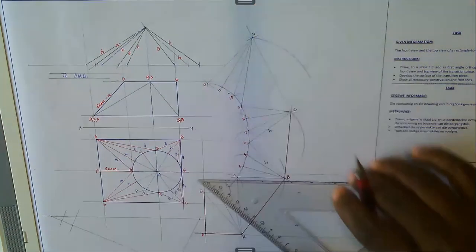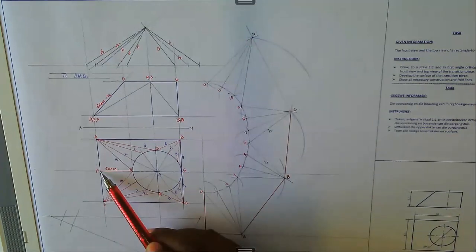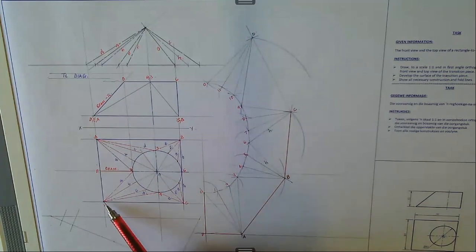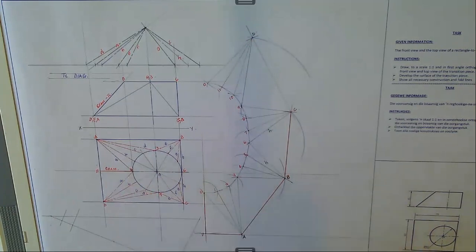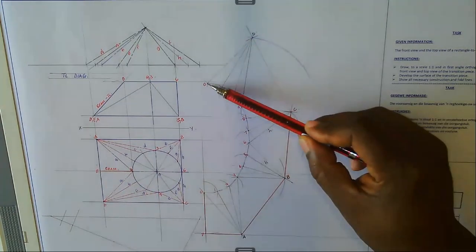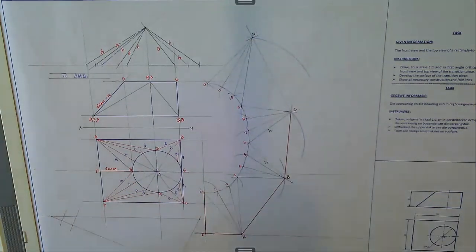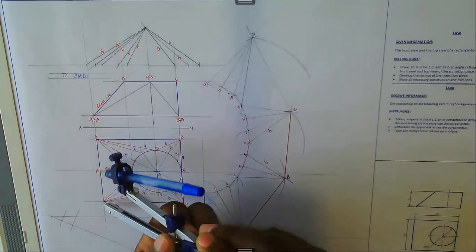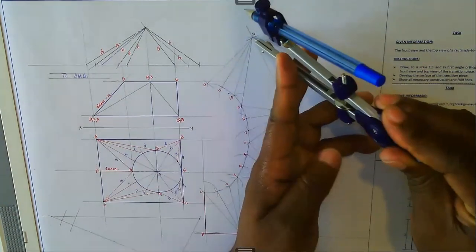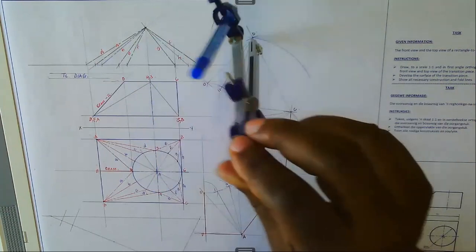Like that. Right. So what we are left with, we are now at D. We want to get to point E. Point E is a description of D to E as well as 0 to E. Right, okay. 0 is already there, D is already there. So all what we need to do is to reach point E. So you take this, which is your DE, which is the true size, stand at point D, and describe an arc like that.